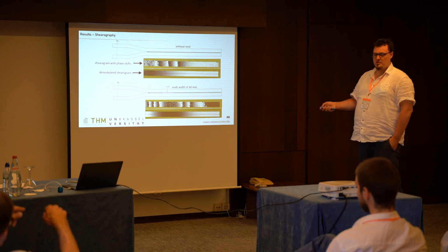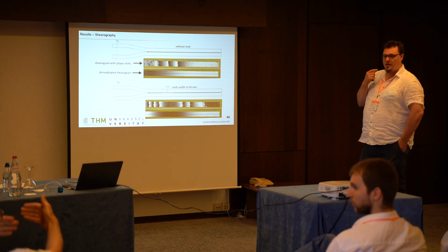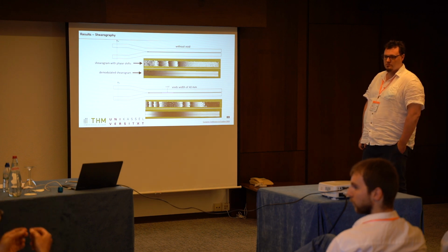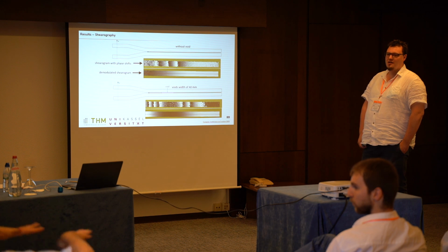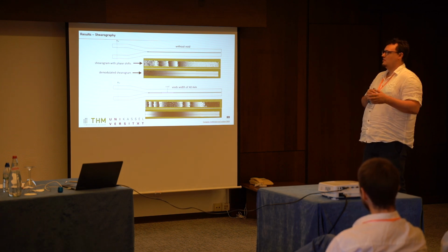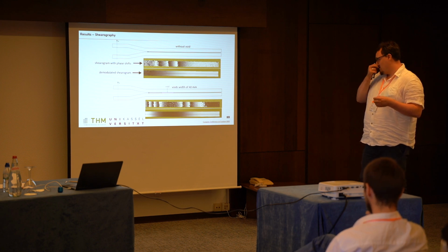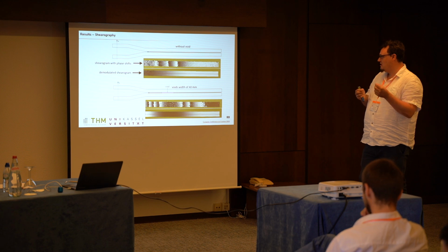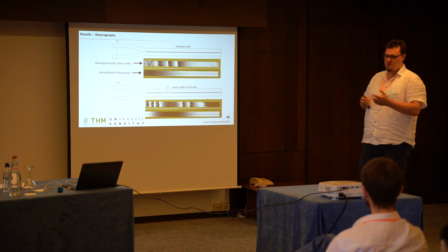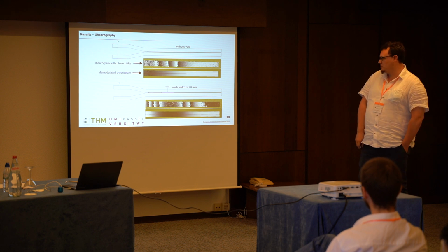This is clear, but I understand. But this is a 2D problem, yeah? But this is not a void, I mean, this is a delamination over the whole width. Yes, it's very large. We did tests before, and we saw that voids of 10 millimeters we cannot localize, and we chose this void.